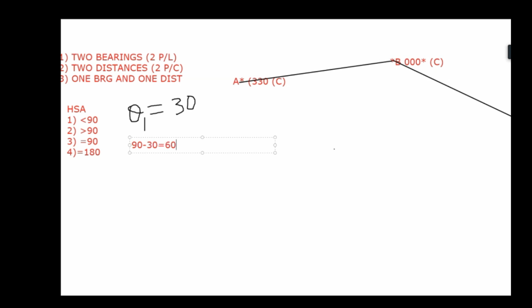You must have done the PZX triangle in navigation, no? Yes, sir, we have done. So PZ is equal to what? PZ is the colat. Colat means the complementary angle of lat, that means PZ is equal to 90 minus lat. Complementary angle means 90 minus theta. So here also the complementary angle of 30 is equal to 60.